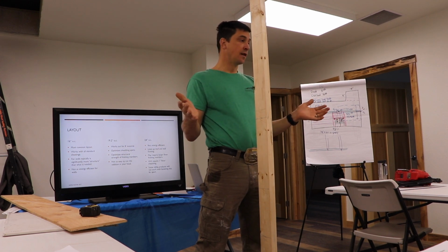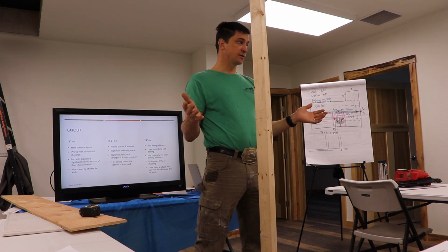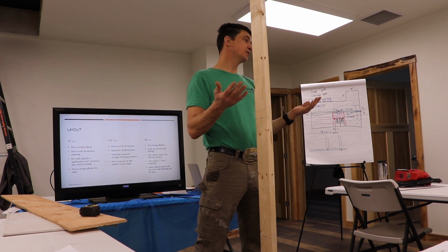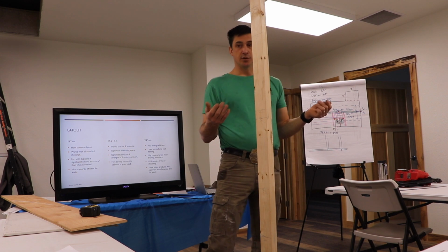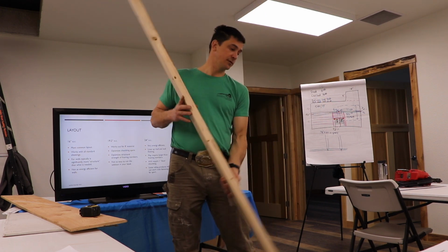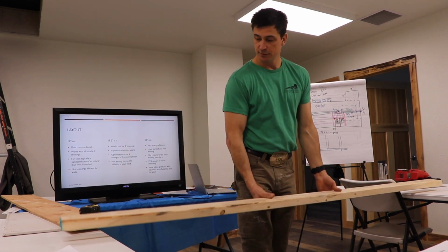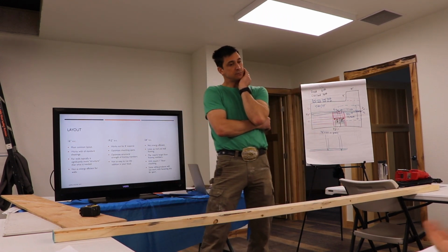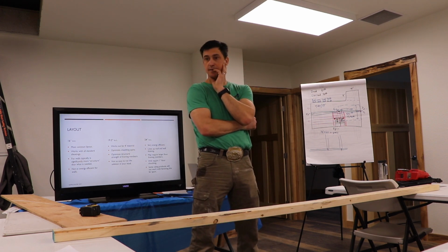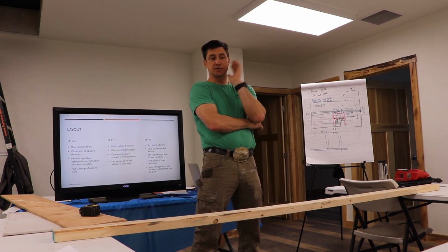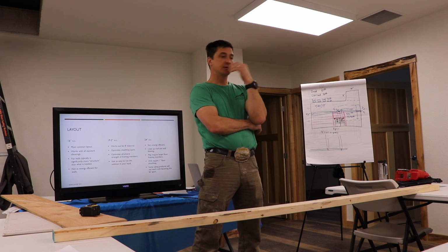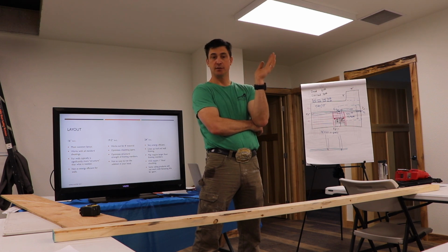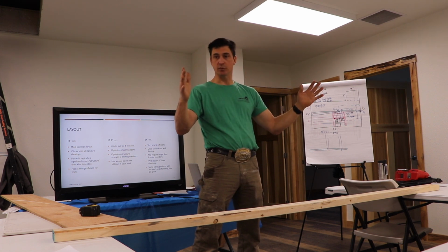You could go a 2x6, 24 inches on center on floor 1, a 2x4, 24 inches on center on floor 2 if you want. Generally, we go with a 2x6 to give a greater insulation thickness, but structurally it's not needed. So like 99% of the buildings that we build, you don't need anything more than a 2x6 spaced at 24-inch centers